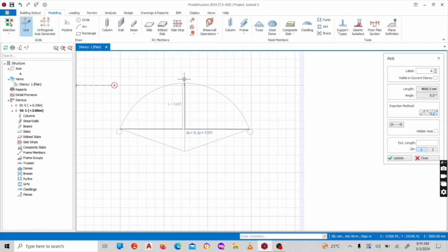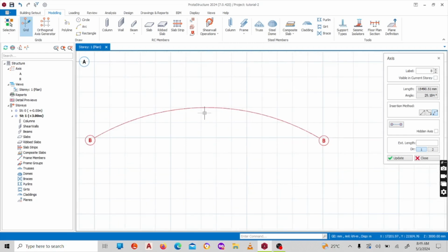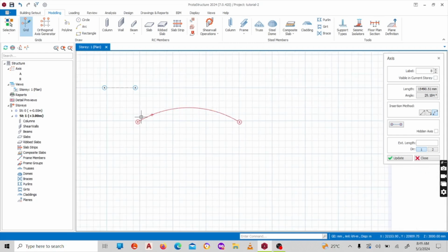In order to get the curvature, you are going to insert this length, which you are seeing in a bell color. Again, if you press Shift F2, the length is 2000. Press enter to give a curvature of 2000.